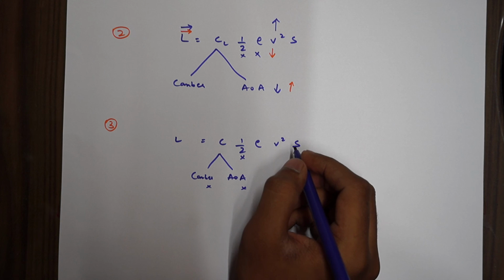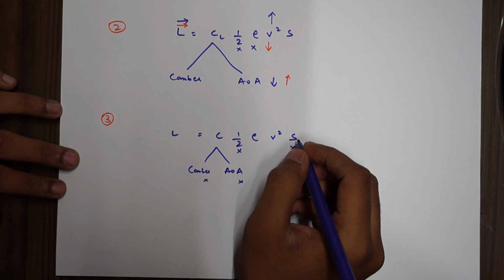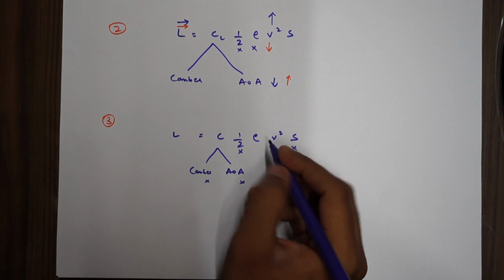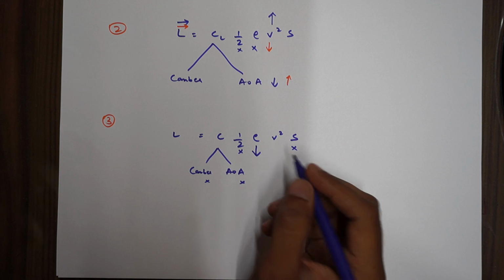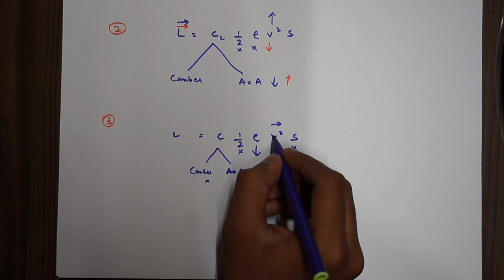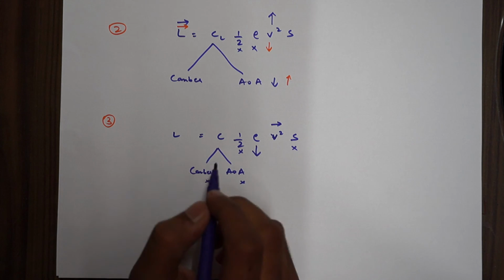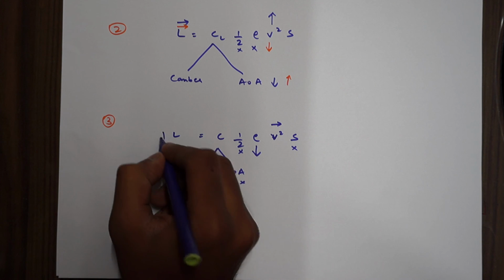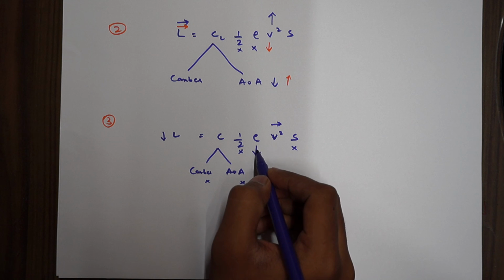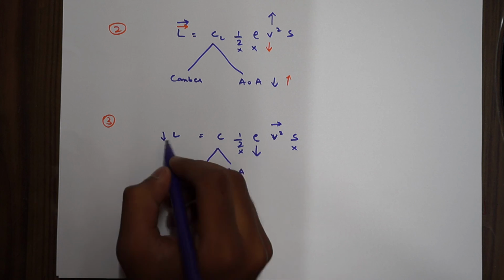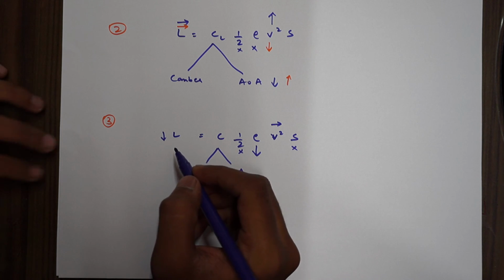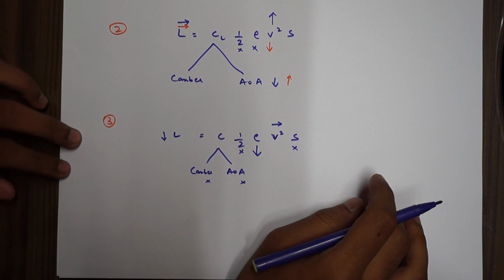Now, as the altitude increases, your density is obviously dropping. But if the true speed is kept constant, the amount of airflow over the wing will obviously decrease, and hence the lift will decrease. So if the true airspeed is kept constant and you're climbing, when the density is decreasing, the lift will also decrease because the amount of air flowing over the wing has reduced. So this is the third application.